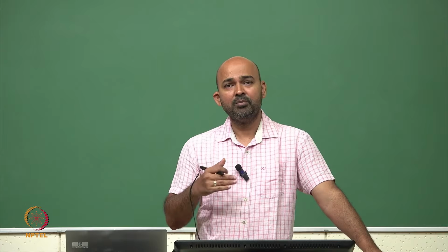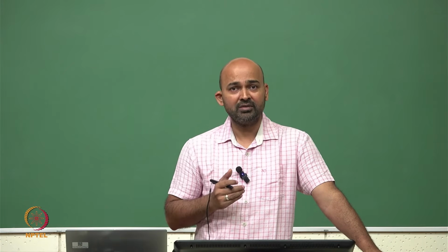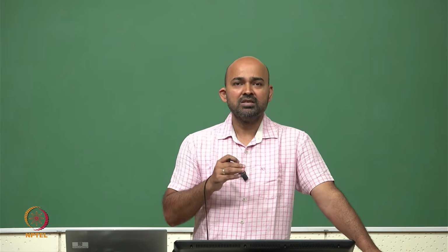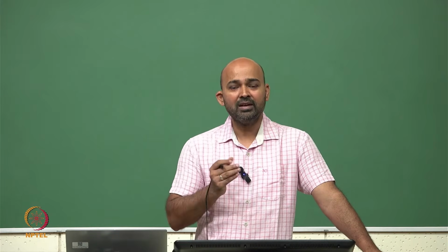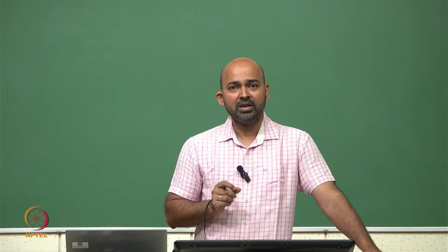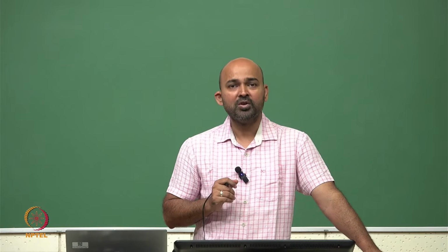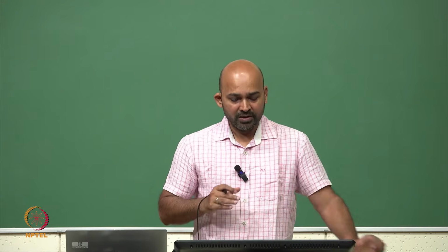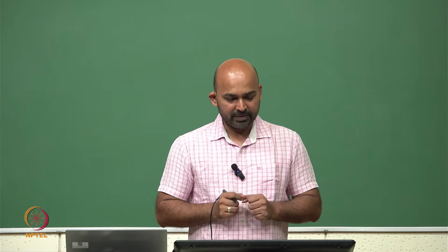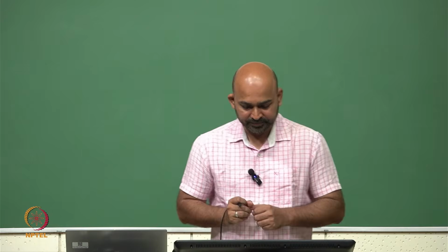If we have MOSFETs and semiconductor devices, these devices are very sensitive to temperature or even other parameters. So, there we need to choose V increment very carefully, so that we do not miss out on any particular type of behavior. So, this is how we simulate using the .dc statement. So, this is the DC sweep.